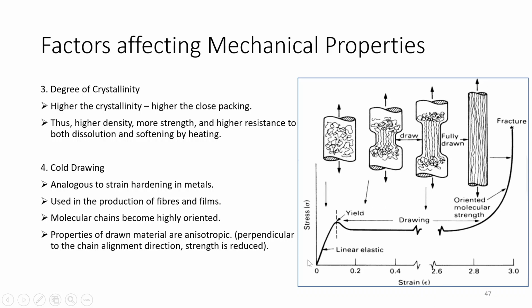And this is what the stress-strain curve for plastic polymers looks like. There is very high ductility up to 3%. Not 3%, this is the strain. After converting into percent, you have to multiply by 100. Yielding will be here. After that the curve goes down, then the cold drawing process will be there. The chains will keep on aligning, so at this particular place your stress will be almost constant.